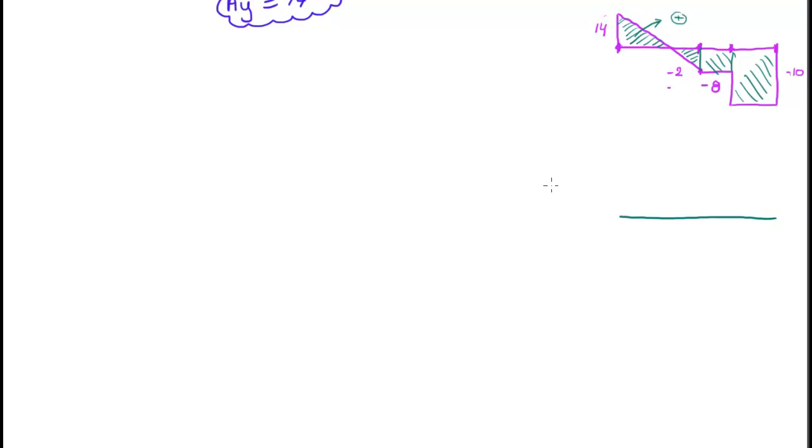Okay, so again, what are the important points now? Of course, it's the beginning and the end of the beam. Now, of course, these points I put on the shear diagram should go down as well. Any new points? Yes, this point is of great interest to us, where the shear intersects with the x-axis. It's a great point to study right here, and this one's going to give us most of the solution, and this is the tricky one, basically.